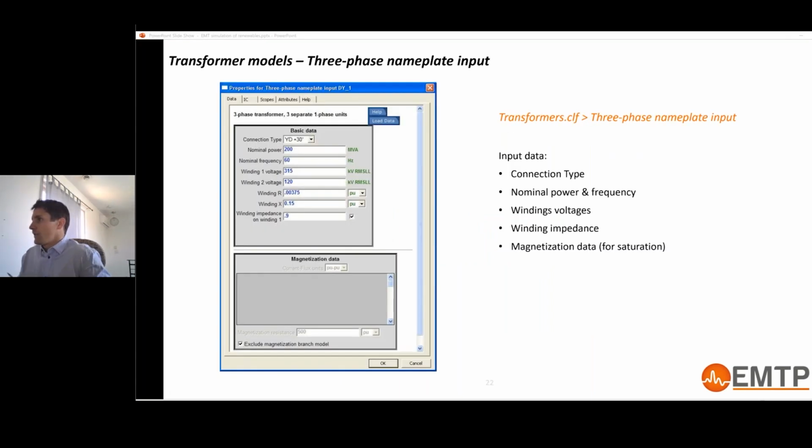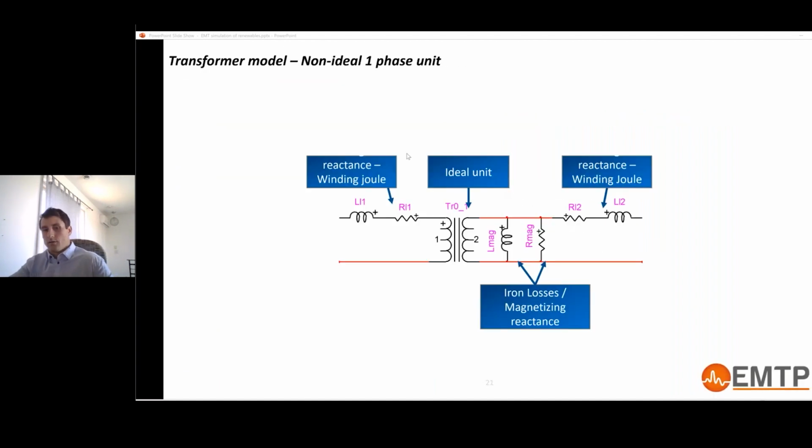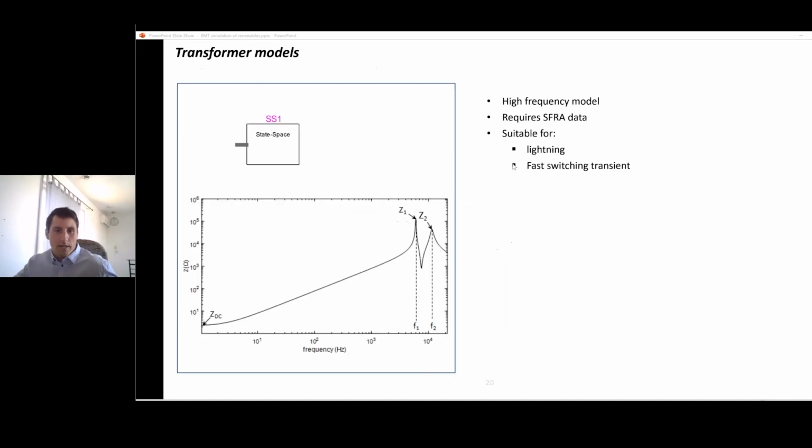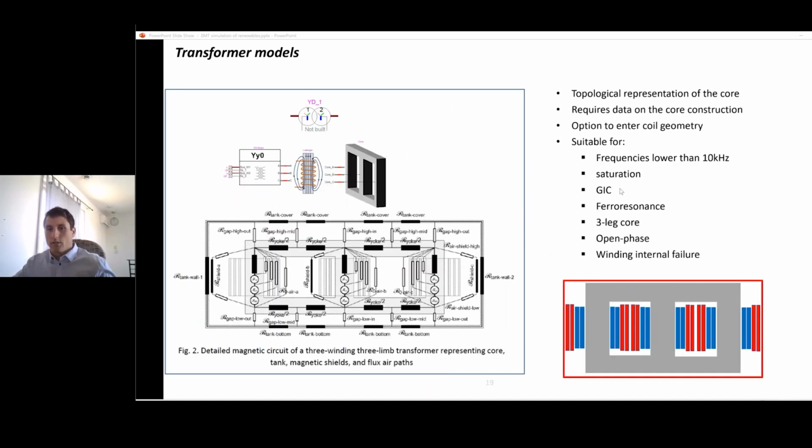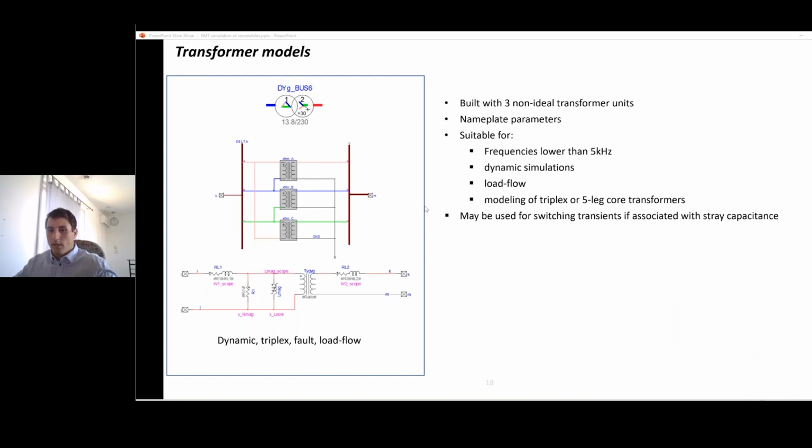Another question here. When doing detailed modeling of the transformer, the information of the core design may not be generally available. In the absence of such data, how far can we go ahead with the modeling? Or do we make some basic assumption to proceed? Well, good question. Like I said, most of the time for renewable energy, we will use this representation here because we're interested in short circuit studies, stability studies, and so on. Now, if we do the studies that I explained here, which are saturation, ferroresonance, and so on, the other model here may not be valid anymore. Then you will need this one.